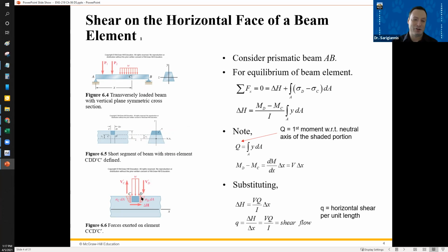First of all, we're going to break this down, and remember your forces change with depth, right? Remember, your normal stress is highest at C. As you go closer to the neutral axis, your normal stress, not your normal force, decreases, and that's what's shown by this drawing here. It's going to go to 0 at the neutral axis.